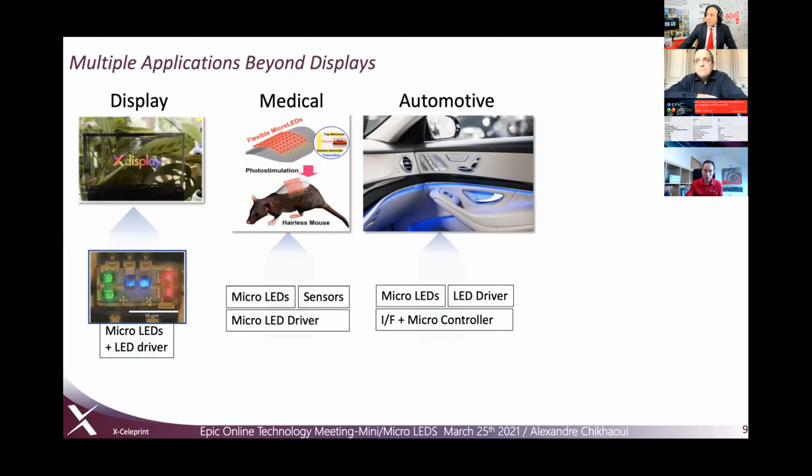And all the integration methods of light guides, all the control methods will have to change because the number of LEDs is growing. And here comes the need of potentially intelligent pixels, which do not only contain the light generation of micro LEDs, but also have the LED driver like the active pixel, and we can also have a microcontroller and bus interfaces. So this is also another application of 3D HI micro systems that could go into automotive.